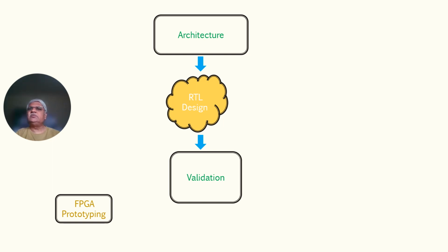In this emulation, it depends upon the model accuracy, on how the SoC design is getting realized through virtual prototyping, and then we ensure that this is properly checked. There are several emulators which automatically map the RTL representation of a design to their internal programmable gate array, and then perform the RTL verification.